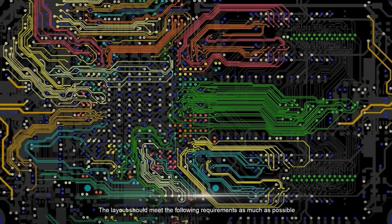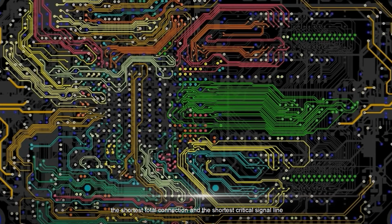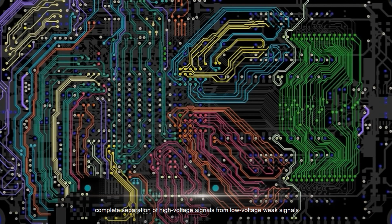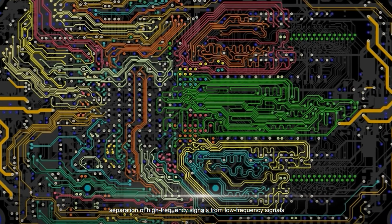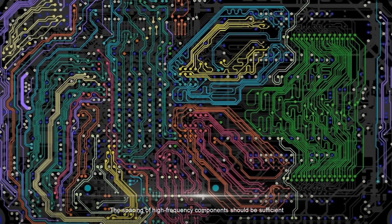5. The layout should meet the following requirements as much as possible: the shortest total connection and the shortest critical signal line, complete separation of high-voltage signals from low-voltage weak signals, separation of analog signals from digital signals, separation of high-frequency signals from low-frequency signals. The spacing of high-frequency components should be sufficient.